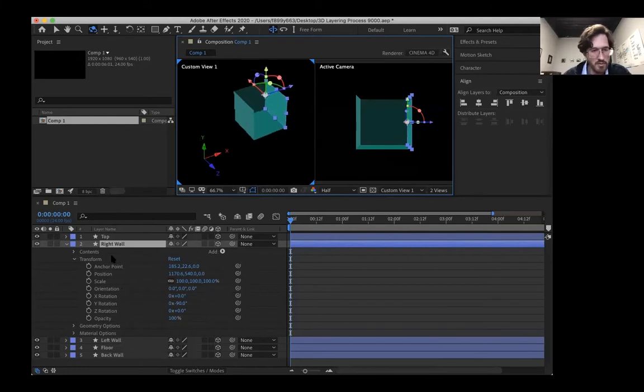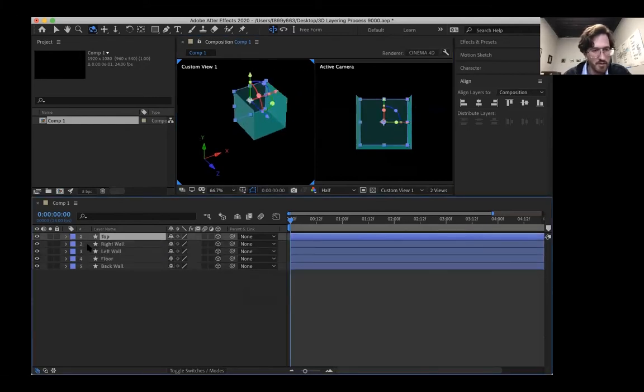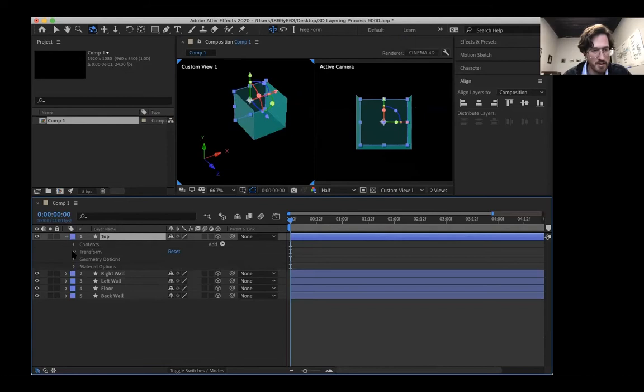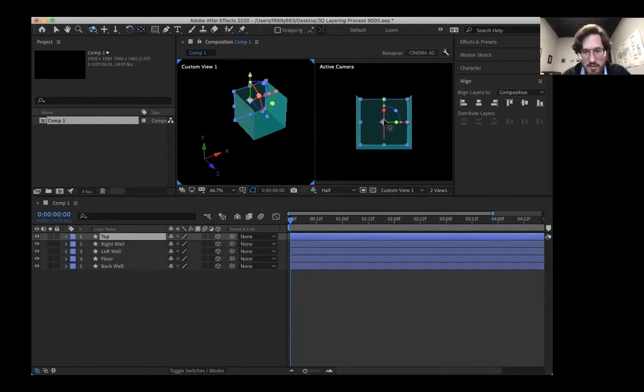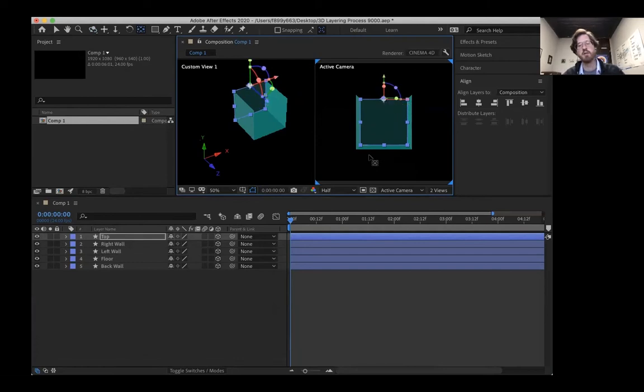So now we're going to go to the top of our wall here. And again, we need to move this orientation of our anchor point to the top center. And it seems like I'm having to reselect my anchor point more than once and then hold down the command button right away to get it to snap. So I'm having to move it up, then let go, click and drag while holding the command button to get it to snap there. I hope that's working for you all.